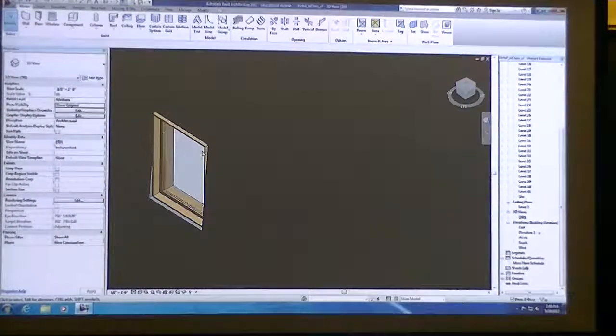Revit doesn't know how to handle that because normally you try to put in a window straight anyway. We can later talk about on Tuesday, we could make an opening cut and then place an adaptive component in there that is your window and can slant to, let's say, the midpoint of this frame or even the exterior.